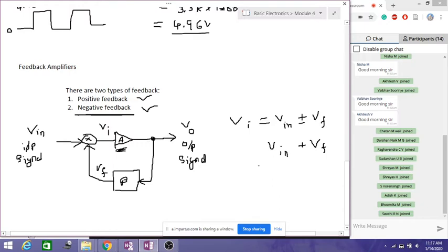Whereas oscillators are circuits where we generate oscillations of the desired frequency. There we go for positive feedback because we are not applying any input. They are self-generated oscillation circuits, so there we give positive feedback. That is why it will generate the oscillations.